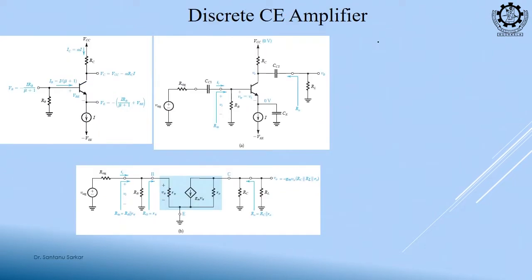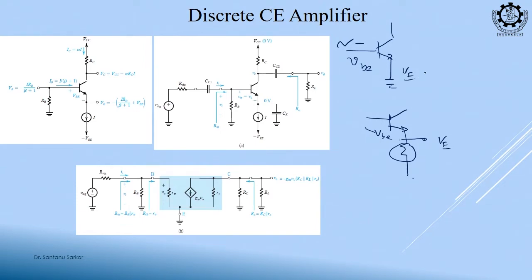Can you recall? Previously my circuit was like this. So, it was my VB, right. So, I have no control. If this is increasing, my IB will increase, my IC will also increase. Now, what have I modified? I have put a resistance. Now, you see this is my VB and there is an emitter voltage now. Previously emitter voltage was 0.